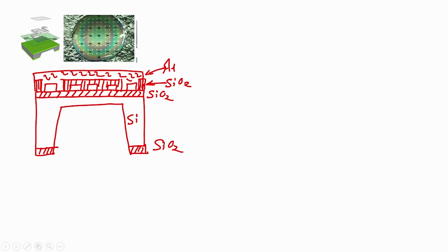Okay. What is the next step? Next step is we have to create interdigitated electrodes on this structure. So, we will deposit a metal. Let us have this pattern for our metal. Our metal is nothing but aluminum. This one would be our SiO2 from PECVD. This is our SiO2 from wet oxidation LPCVD, and this is our diaphragm, 100 microns. Now, we want to create interdigitated electrodes.